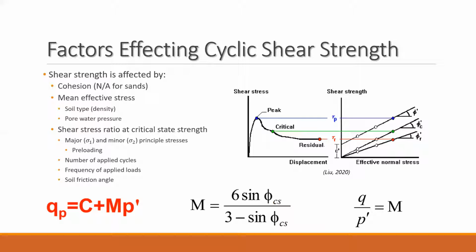By investigating these factors further, it is found that they are also influenced by properties such as the soil material and density, pore water pressure, principal stresses, and the number and frequency of the applied loading.